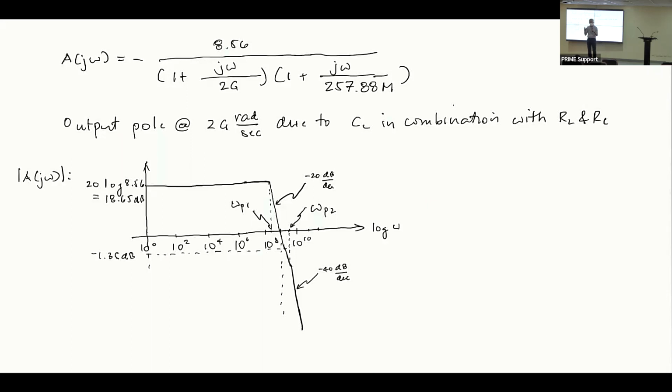But at DC, what is a capacitor equivalent to? It's an open circuit. If it is an open circuit, ibig sabihin, none of the input will enter the amplifier. Kasi may open circuit ka ron, no? At DC. If none of the input can enter the amplifier, what is my gain? My gain is 0. So you can see that this is not exactly accurate at low frequency.